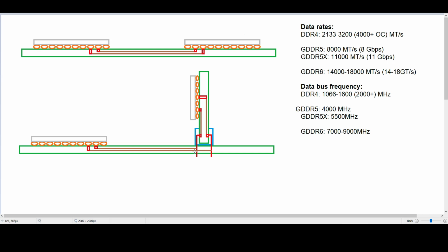And we already see today that GDDR5 and GDDR6 are extremely power hungry interfaces, even when you have a good, simple memory trace layout. We still have massive power hogs for the memory transfer in GPUs. There's a reason we're trying to go to HBM, because it means that the signal integrity is much easier. We can have a wider interface, rather than having a faster conductor, we can have a wider conductor.